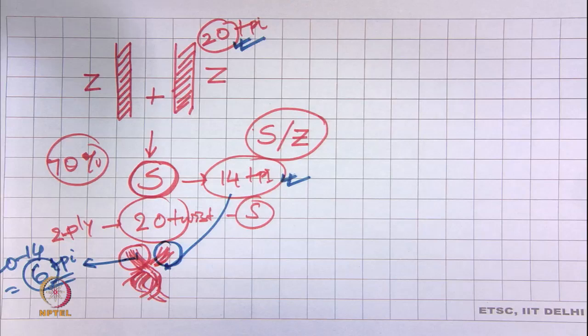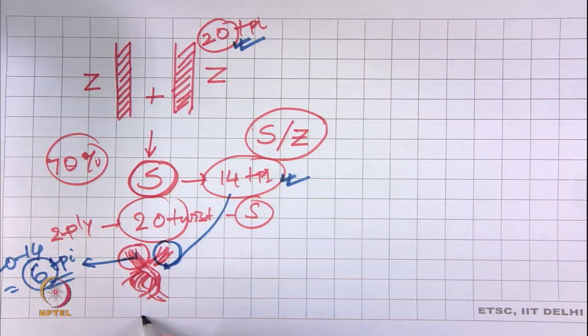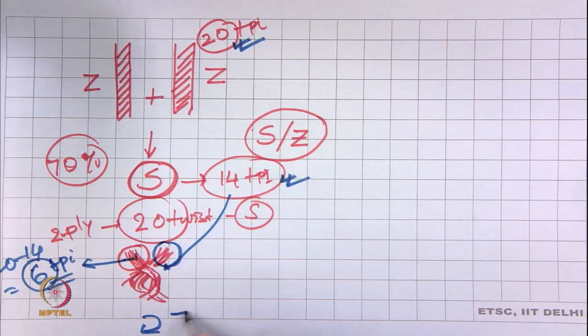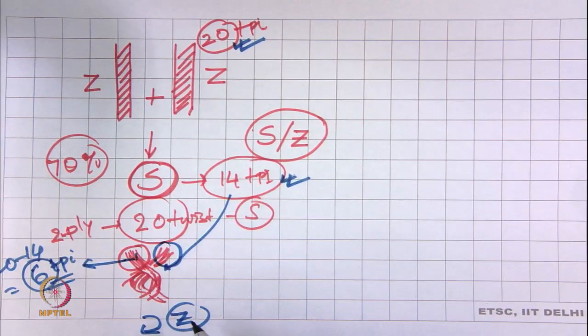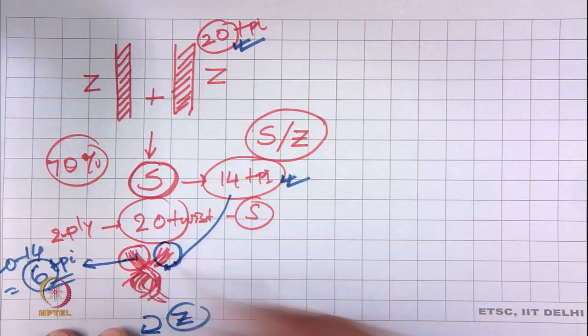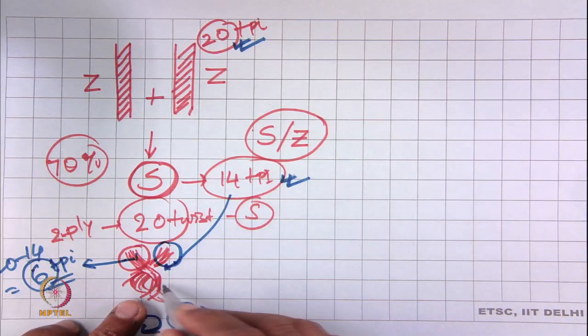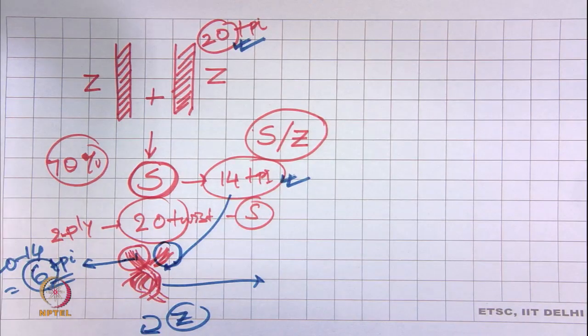Again if we untwist, then for every twist we untwist, one twist will be added again to the single strand, because we will be untwisting in the z direction. In the 2 ply yarn, once we try to untwist, it will keep on adding twist in the single thread, until the plied yarn becomes parallel.